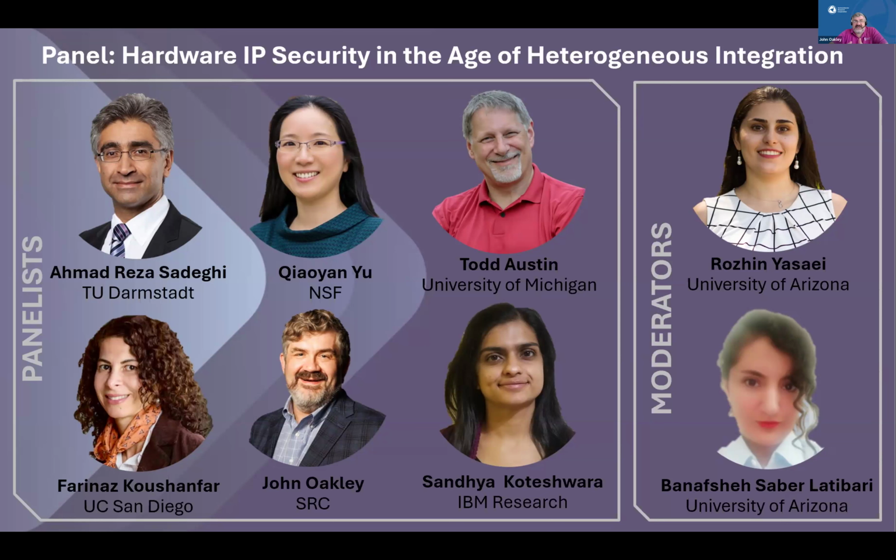You're going to have through silicon vias, through devices, which actually opens up a whole new game because it's not difficult to measure current going through those things from the chip that is the interface. If you're all integrated in one chip, then you can see if someone put a monitor there. But when you have these heterogeneous systems, it's hard to see these monitors or even detect that they exist. All you can see is a little bit of energy loss maybe, and that's resistance, which could just be a byproduct of having a TSV or something.